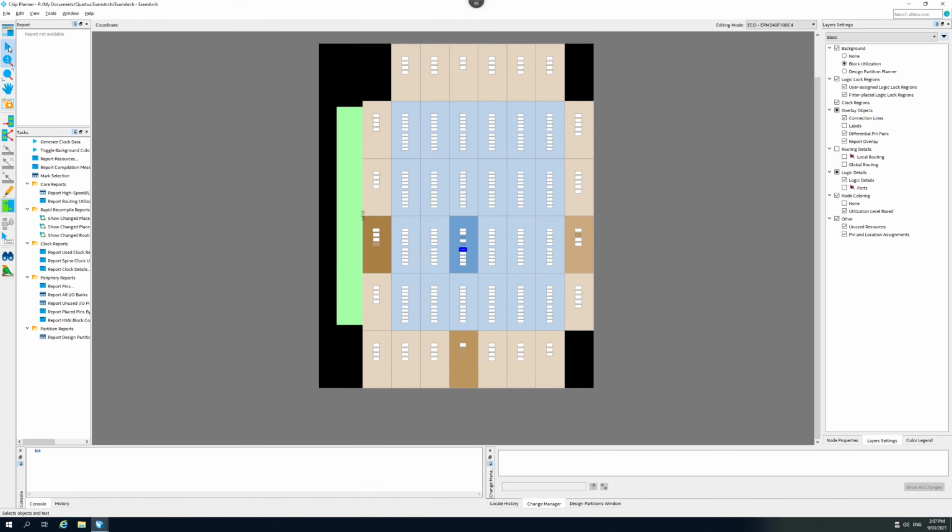And what do we have here? So around the outside here, we have got our input-output buffers, input-output logic. And we see that we are using 1, 2, 3 different input-output blocks. And inside each one, we can actually see that we're using this pin, and this says it's node C. So our input C is actually going to be connected to the pin that comes into here.